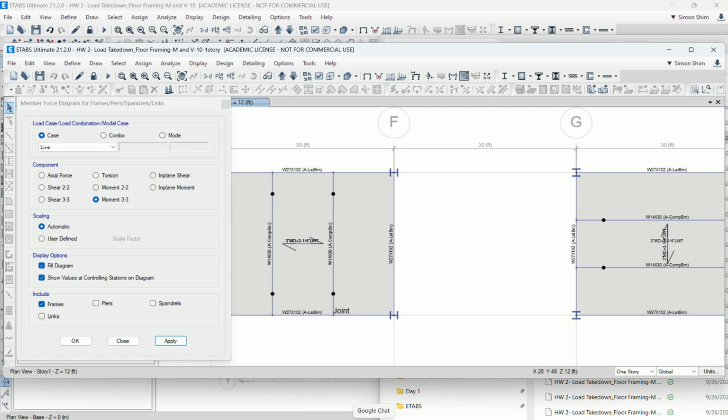But what I want is for you to bring this all together. Physically, how the building is constructed, and the associated load paths. You need to properly define the load path. That is the most important thing. The next step is mostly straightforward. But up to here, right?